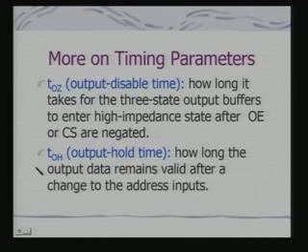Now, these parameters that I have discussed in detail are primarily read timing parameters. Now, what is their importance? If I am connecting a processor to a RAM memory block for the purpose of reading and writing, obviously, the timings have to be consistent, and these parameters determine the speed at which I can really read data from the RAM or write data onto the RAM.